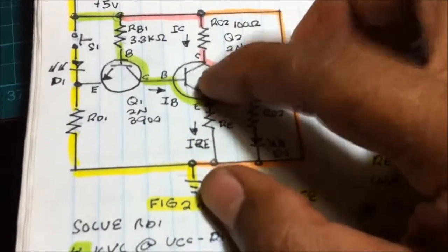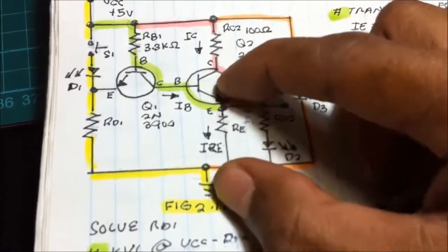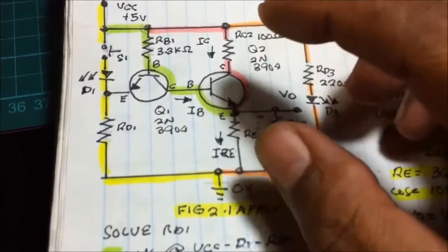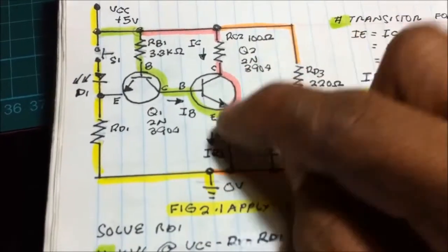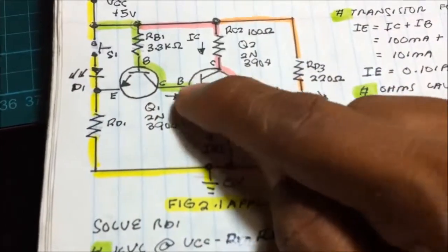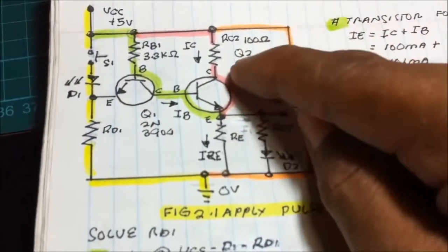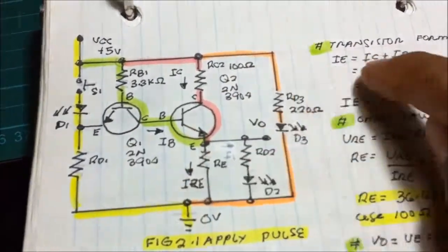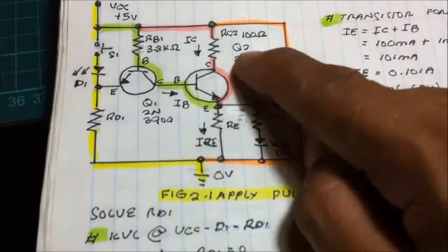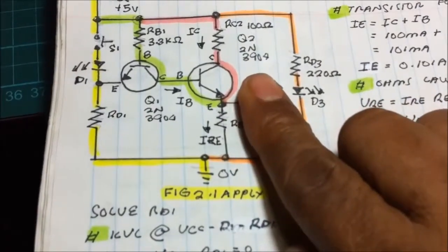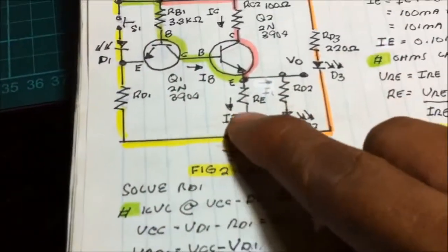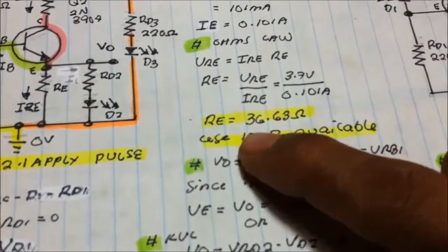If you have a resistor here, we need to have a resistor here, because this is our output or the load resistance or the output impedance. The output resistance, we need to connect a resistor here, and the current that flows here when the transistor is forward bias is 100 milliamps, the current rating of the transistor in switching application of this type of transistor. 100 milliamps total current without a load. Computing that without a load, we got 100 ohms. Now we know the value of resistor, 100 ohms.